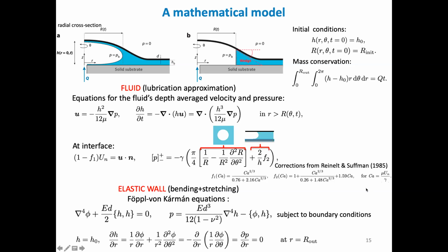But we did verify this against the Stokes equations in particular regimes, and we also have very good quantitative agreement with experiments. So we were happy with the ad hoc changes that we made to our model. And so what we were modeling with this is an expansion of the bubble in an elastic Hele-Shaw cell, which can account for these thin films left behind as well. Okay, so that's the complete set of equations we have for this problem.